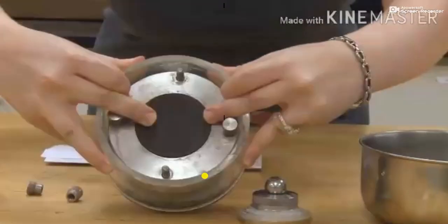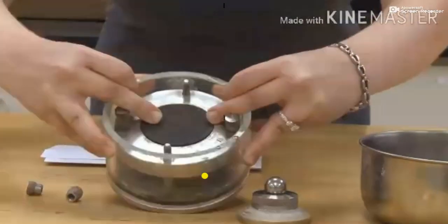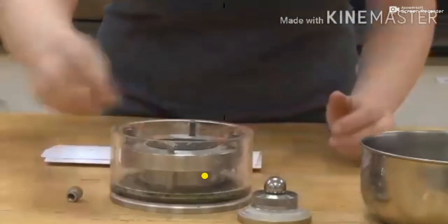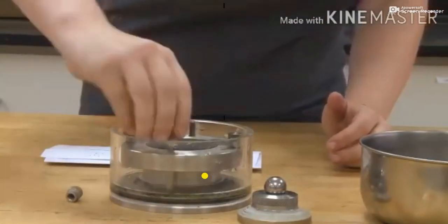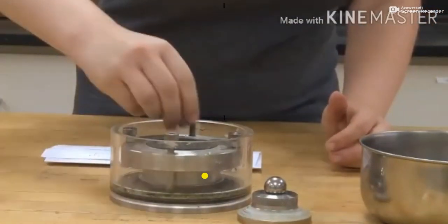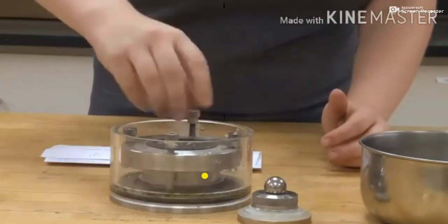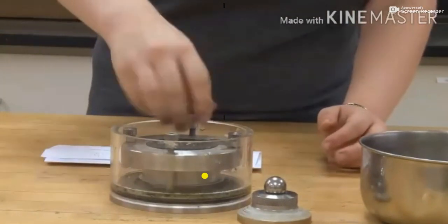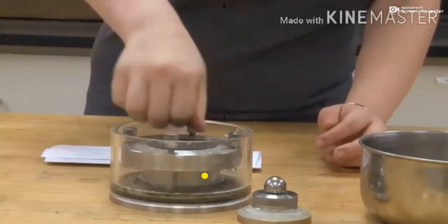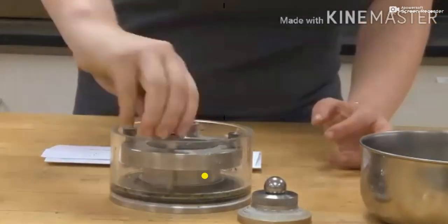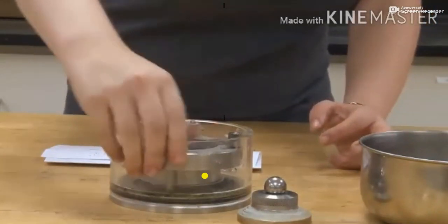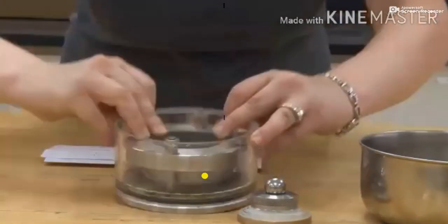So our sample is totally laterally confined, confined all around. No pressure will come from the lateral direction, the x direction, and we can allow load only from the vertical direction, the y direction. And this is the one dimensional consolidation test.